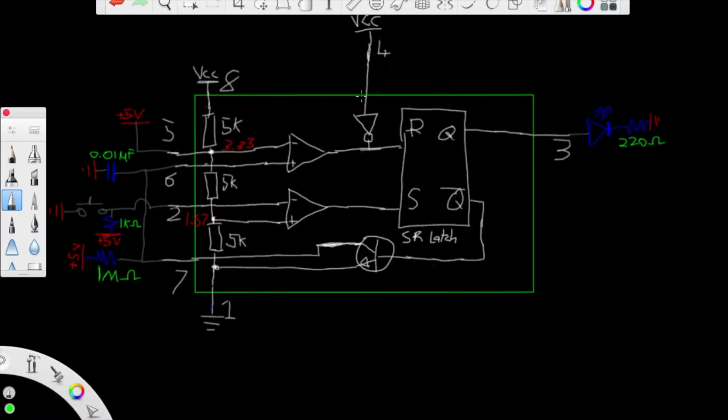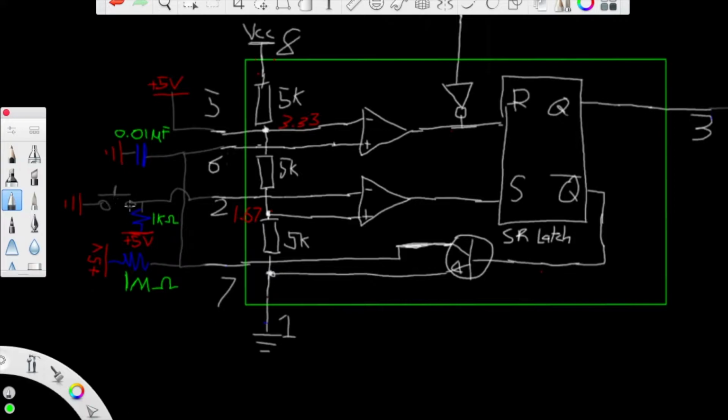So I've got a monostable set up with the 555 timer this time, so I'll run over what's on the outside of it. And if you want to know more about what's on the inside, in the last video I did on the astable 555 timer, I explained it all. And so pin 1 is connected to ground, pin 2 is connected to the output of this button, which is normally pulled up, but when it's pressed it's tied low.